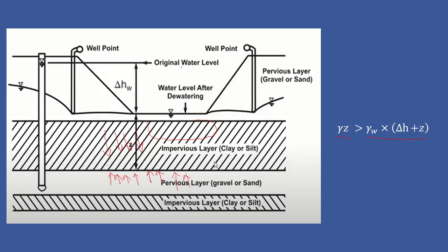That's why if you're going for excavation, you need to check for the lowering of the water head also, so that an equilibrium is maintained. Both conditions should be permissible, but your uplift pressure should not be greater than your overburden pressure. That should be the minimum requirement. Your overburden pressure should be greater than your uplift pressure, or both can be in equilibrium, but that is a critical condition, so it is better to keep your overburden pressure higher.